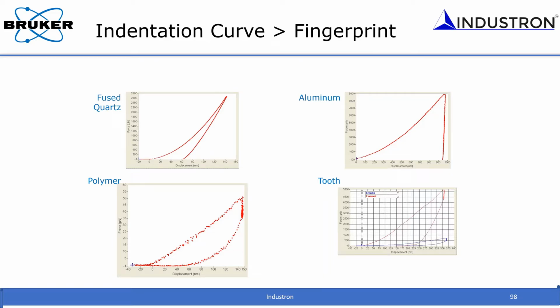From the known force and the displacement response, we can calculate the stiffness of interaction when you are in contact with the sample. And from that, we can deconvolute properties like hardness and modulus. That is what we discussed in the last meeting, right?